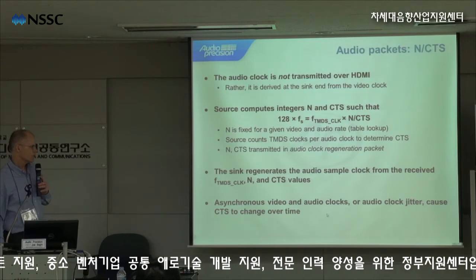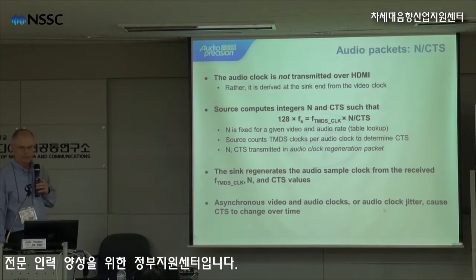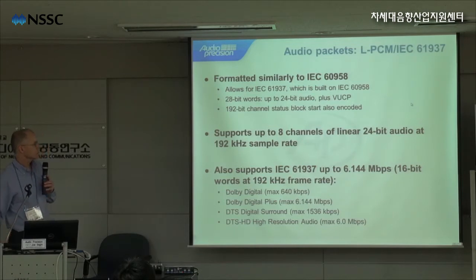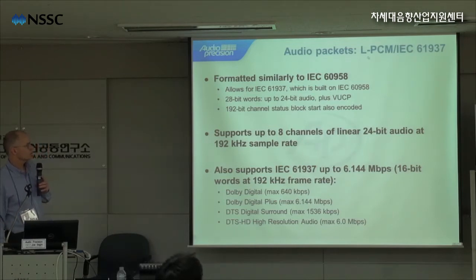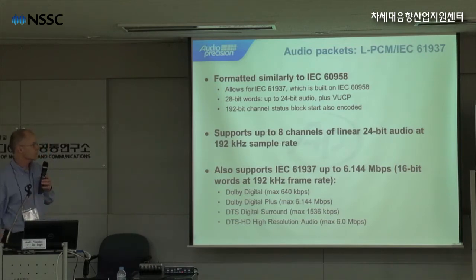So asynchronous video and audio clocks, or audio clock jitter, can cause CTS to change over time. Now the audio packets use what's called LPCM, which stands for linear pulse-code modulation. And this follows the IEC 61937 standard. It's formatted very similarly to IEC 60958.